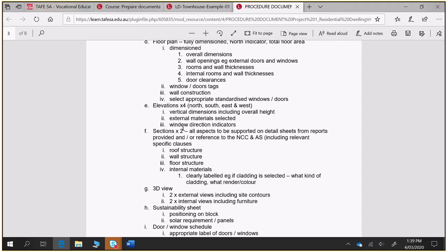Okay, it's a trussed roof, but it's single lines, which says this doesn't tell you information about where those webs are. In terms of looking at the internals, it might not even be a truss roof because at the moment what it's showing is a raked skillion on 2 sides almost effectively. So you don't know where it's going to be, and that's not a truss roof. I can't remember whether it says truss roof in the specification or not. I think it is. From memory, it's a truss roof.